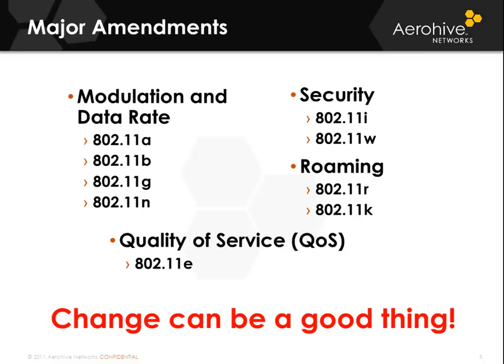802.11g was ratified for that purpose. 802.11g uses extended rate physical OFDM because it extends the rates of OFDM into the physical space of 2.4. It also has backwards compatibility methods to work with legacy devices and protection mechanisms in the event that there are non-members using legacy technology in the surrounding airspace.